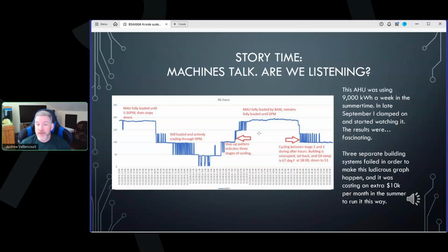The human respiratory system cannot tell the difference between 450, which is what fresh air is, and 600. There's no discernible difference other than the amount of energy it takes. When you're doing energy audits, generally what I've found is that in any building with 10 air handlers or more, there are at least 2 economizers that are screwed up. They're always screwed up.